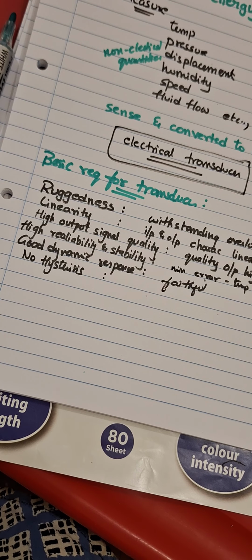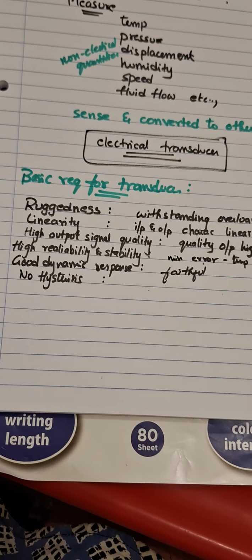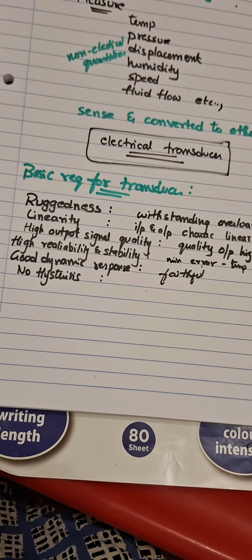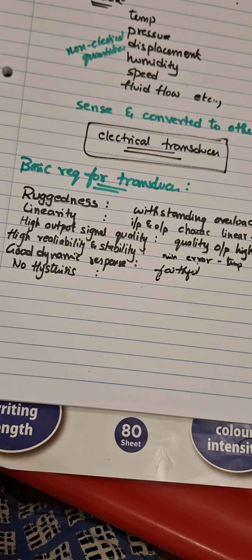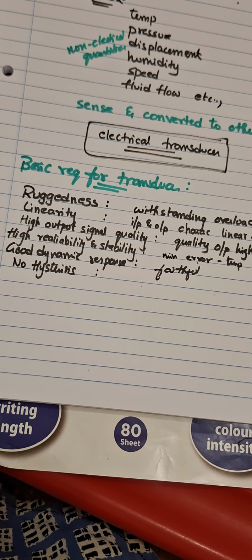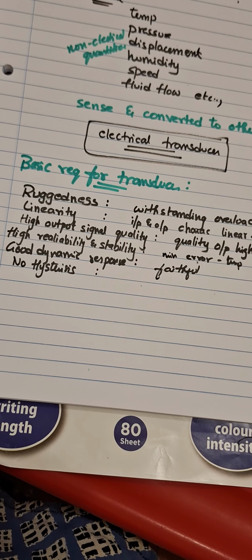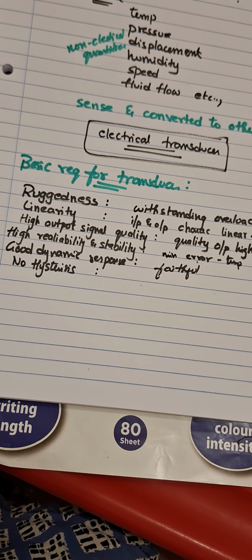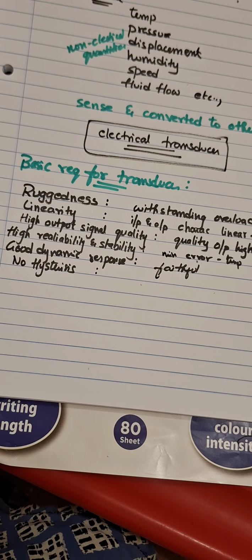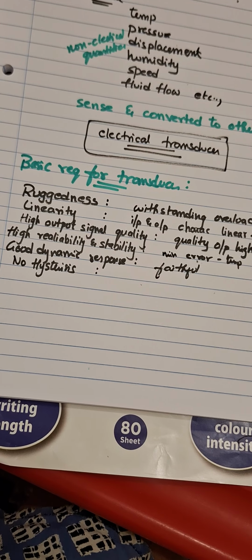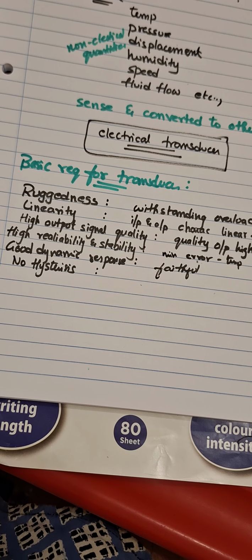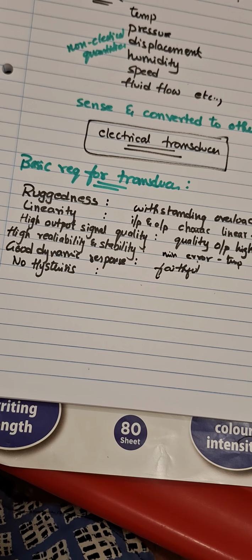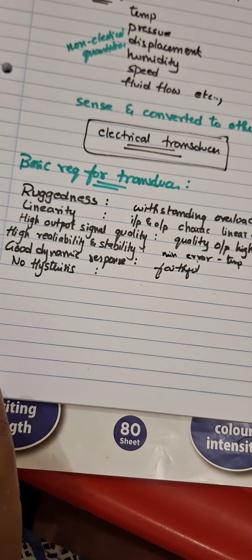For example, you're varying a resistance, like how you did in the Wheatstone bridge experiment. When you're doing that experiment, you are supposed to vary the variable resistance, right? You shouldn't be very fast, and in the same way, you shouldn't be very slow also. That small lag can make some difference in the output. That is called hysteresis, and this shouldn't be there. When you are varying the input from a low signal to a high signal, or from high to low, depending upon your requirement, it shouldn't have any hysteresis.